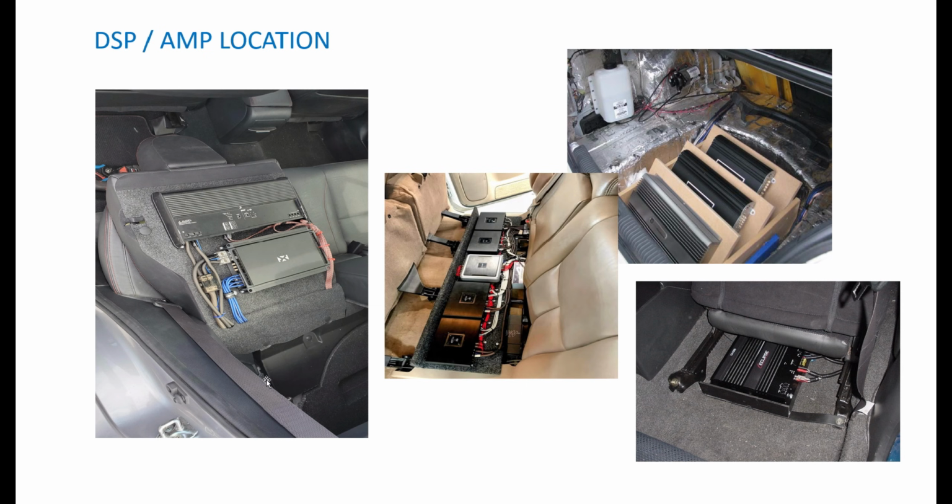So once again, when you're looking at your car's particular design and features, you've got to think about whereabouts you're going to put your DSPs and amps, right? And keep in mind that you're going to want to make sure that they don't overheat, so ventilation, and being able to access them easily, because something will come unplugged one day, or you might need to reset the gains for some reason. Not having to take the car apart just to get to your amplifier or DSP is always a great thing.